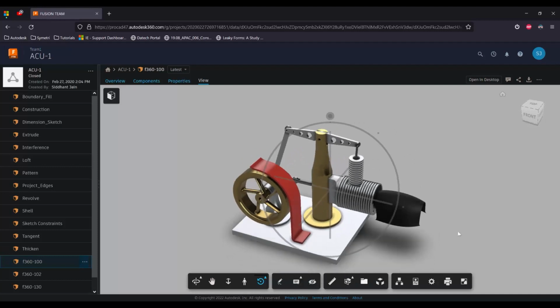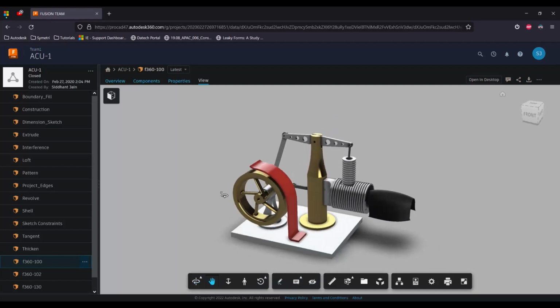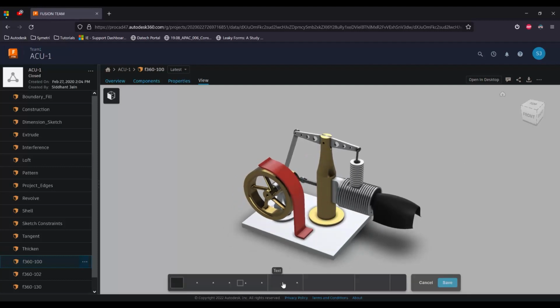Also, just to let you know, your settings that work inside Fusion 360, such as scrolling to zoom in and out of the model, also hitting the shift key along with the middle mouse button will enable you to rotate the model as you see fit. We've also then got our markup options, where essentially we can add in a bit of text.